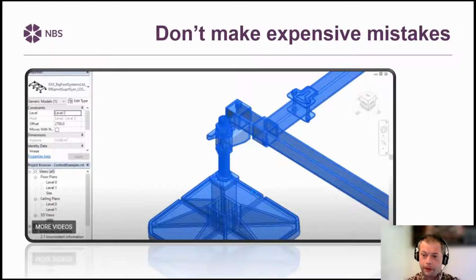Now, the key thing with BIM is that if you're adding all of these different components into the model, they all have file size. The greater the detail within that model, the larger the file size typically is. With this particular example, you can see that we've got screw threads, nuts, and all the different fixings associated with it. The file size for this would be absolutely massive. From a manufacturer's point of view, whilst this would be great for manufacturing, you can do your CNC details, etc., from the CAD file.